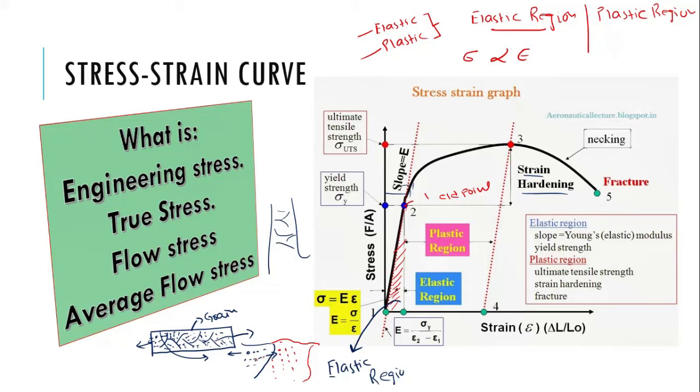So this movement of the layers of atoms is restricted by the change in the arrangement of atoms in the other grain, as there is a natural wall created because of the change in arrangement. So this change in arrangement restricts the movement of material. To break this resistance, we need to apply some extra force so that the deformation will continue. This is called strain hardening, because the material is getting hard and we need to apply extra force because of the strain produced. So strain hardening is the increase in the strength of the material due to the strain.